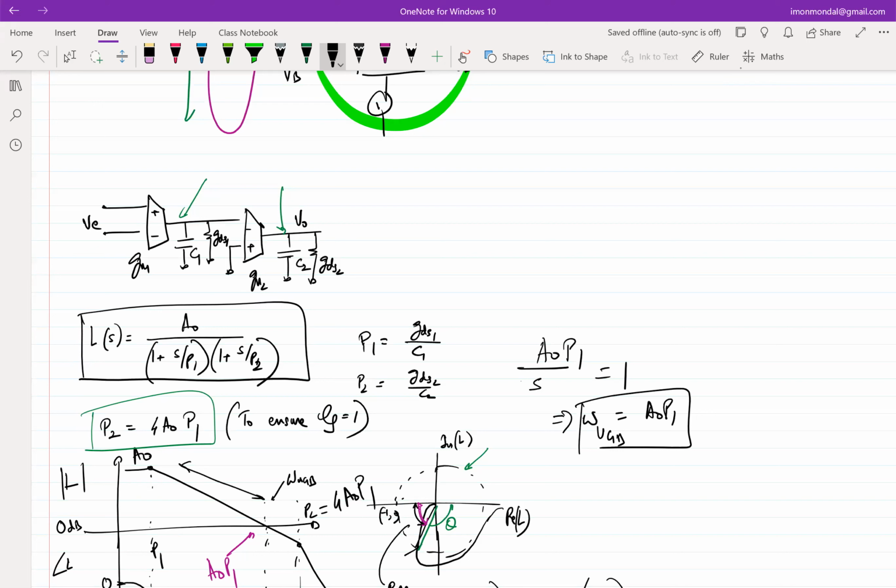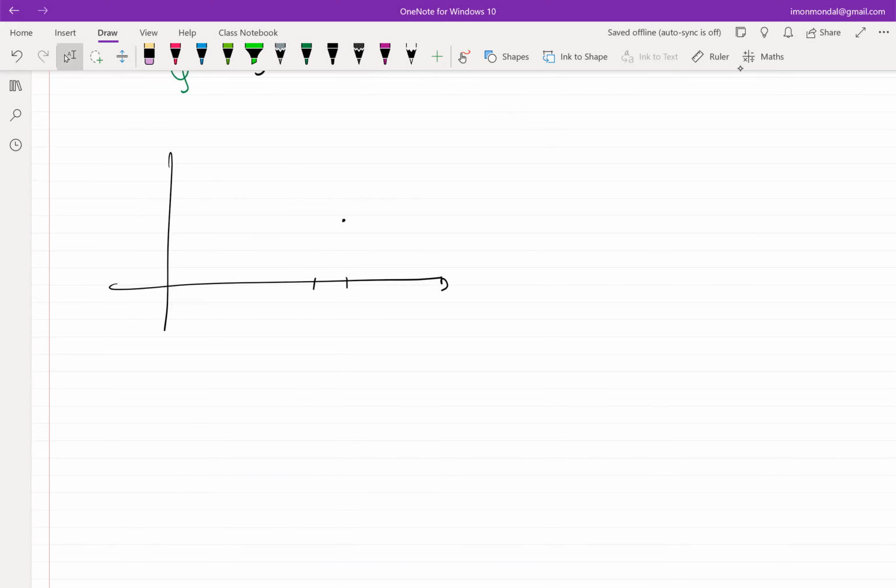So then people thought about it and said, okay, if this is not something that we can do, what else can we do? As engineers, people always figure out a hack of doing things, and one of the hacks is this. If you cannot make a large capacitance, can I trick the system into thinking a small capacitance is behaving like a large capacitance? Putting in a large capacitance effectively means increasing the area, and I do not want to increase the area. The question is, can I make a 1 picofarad capacitance look like a 10 picofarad capacitance without increasing the area?